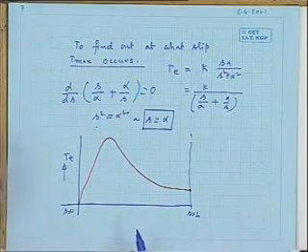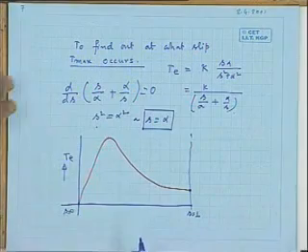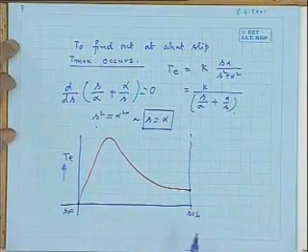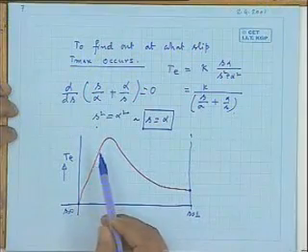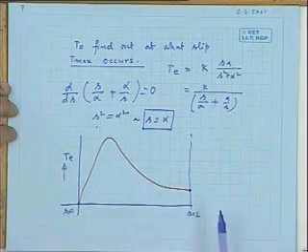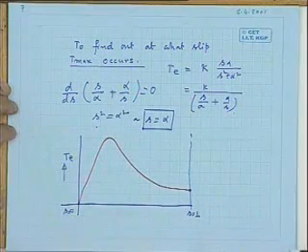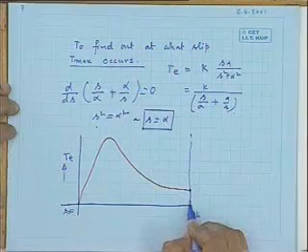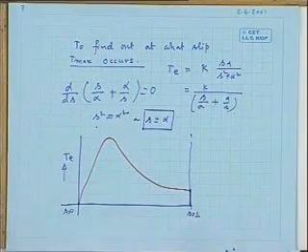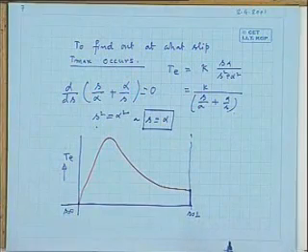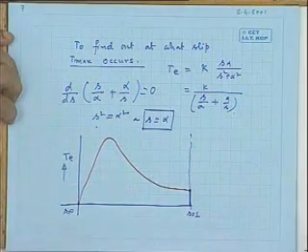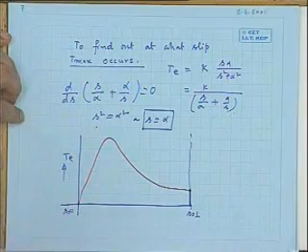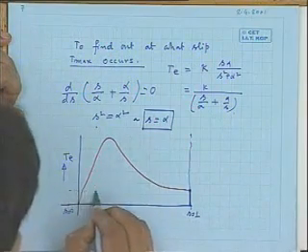Now you just see from the very word go, that is, you switched on the supply, you can now explain in a better way how the machine really picks up speed. For example, if you apply full voltage to the stator winding, that is, rated voltage per phase V1 will be applied, and suppose this is the torque slip characteristic of the machine. How much is the starting torque developed? This much. Now suppose the machine has to start against a load torque whose value is this much.